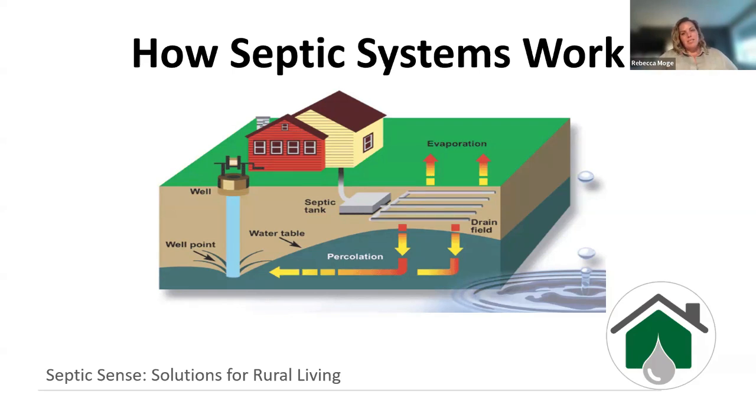So in the photo here, we see the drain field. The sewage would be going down into those laterals that we see and then going down through the soil. We need 5 feet of good soil or appropriate soil in order to treat the effluent before it can hit the water table and be considered potable or safe for use. Under that, we can see the mound there, and that's depicting an underground aquifer.